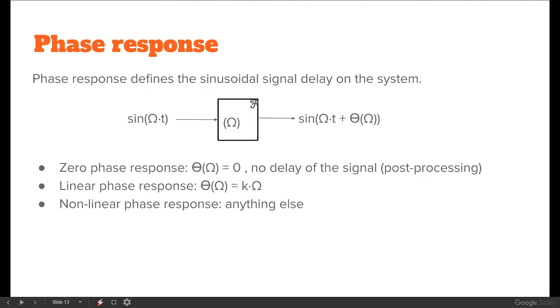You run the same signal through the same system again, and then you reverse the time back, n equals minus n, and you have zero phase response. When you reverse the time, you also change the sign on the phase shift, so the phase shift cancels out. You get a zero phase shift system, which means a zero time shift system.